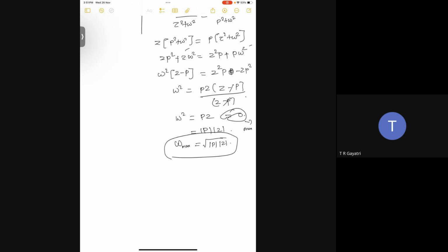So that's it for today. Today we have learned how to design a compensator based on the Bode plot. We did both lead compensator and lag compensator. Whenever you are asked to design any compensator, just find the phase margin shift and look for the corresponding frequency. Move your cursor towards that new frequency, and that's the compensated system's phase margin and gain margin.